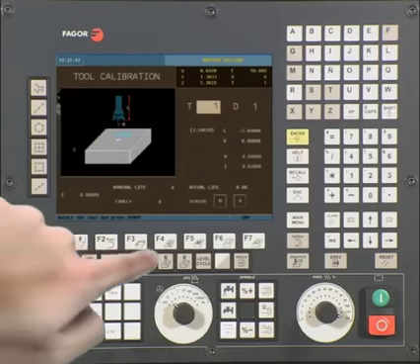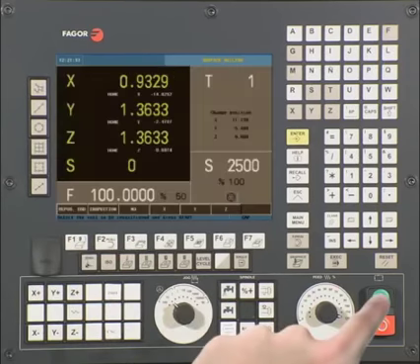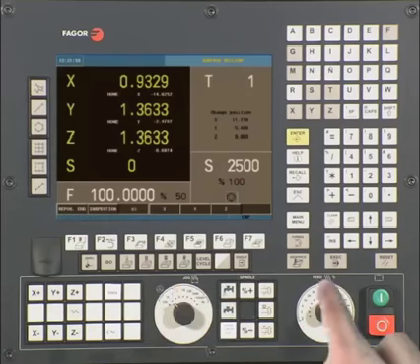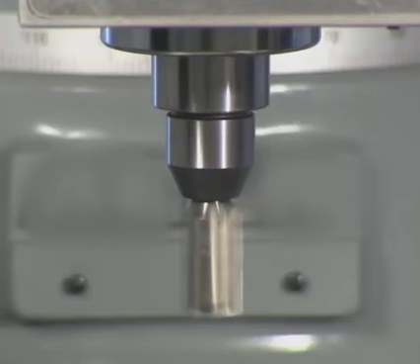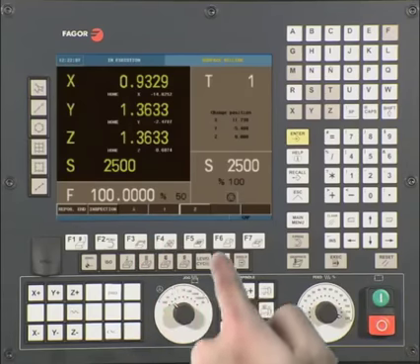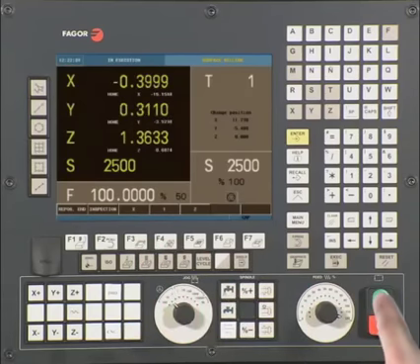When done modifying or inspecting the part, press the Cycle Start button to recover. The CNC will prompt you with options on how you would like to recover. Start the spindle first by selecting M3 and press Cycle Start. Then select X and Y and again press Cycle Start.